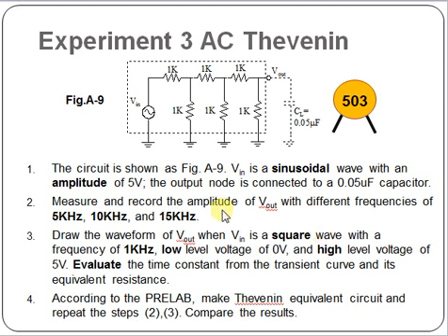In the second part, we will use the square wave to observe the charging and discharging behavior. Recall that the square wave has a high level and a low level. We charge the capacitor during the high level part of the wave and discharge it during the low level part. This requires us to give the capacitor enough time to charge and discharge.